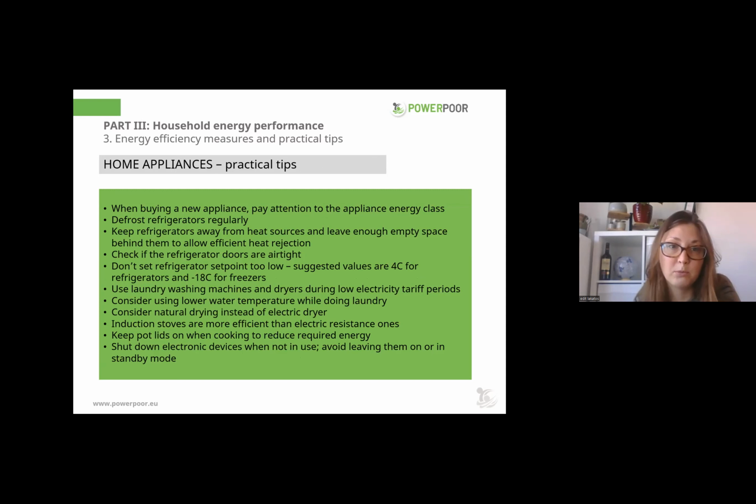In terms of home appliances, we already looked at the energy class that you can check on the label when you buy the appliance. In terms of refrigerators and freezers, maybe it's important information that you should defrost the fridge regularly, keep the fridge away from other heat sources, and leave enough space behind them to allow the heat rejection.